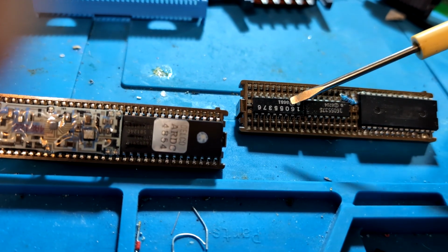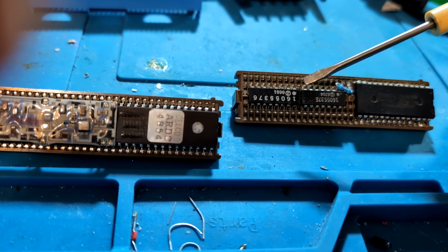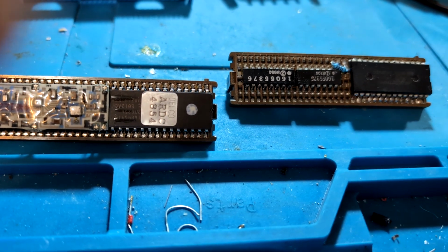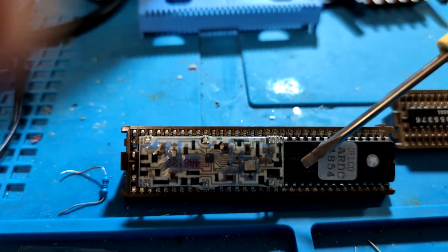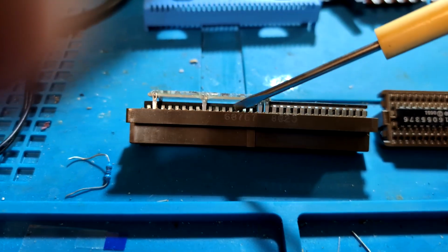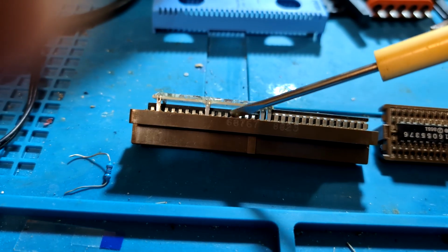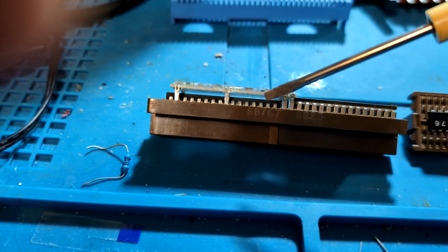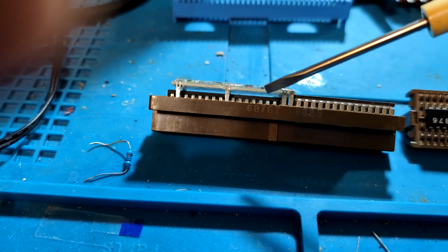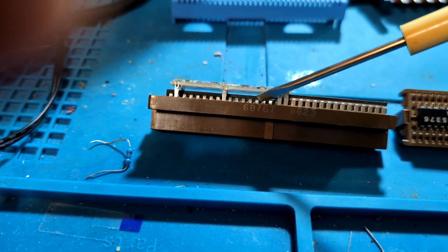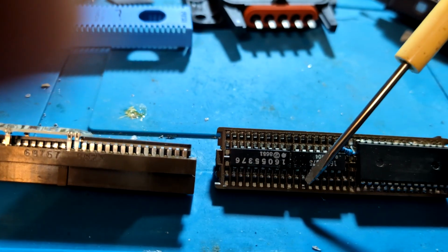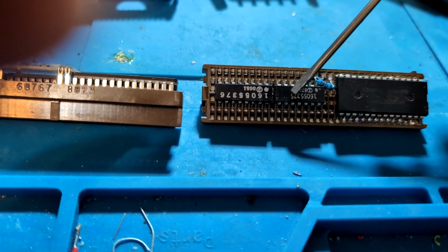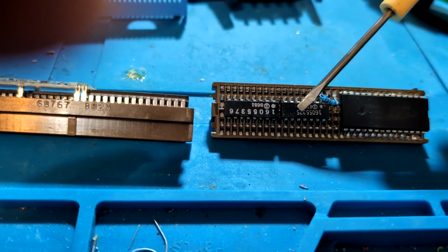And these are specific to the engine size that you're using. In other words, this particular one being a V6 Memcal, these chips are not really likely to run your 350 TPI engine. Or if they did, they would run it probably worse than this one would, which is spec'd for a V8, because this was a 350 TPI MAF Memcal.